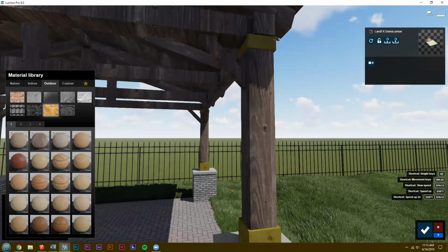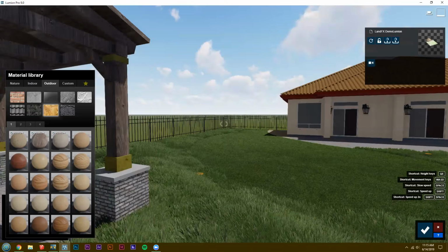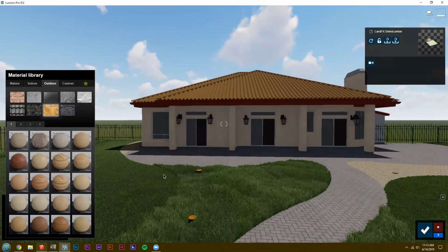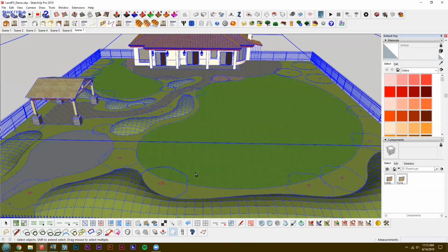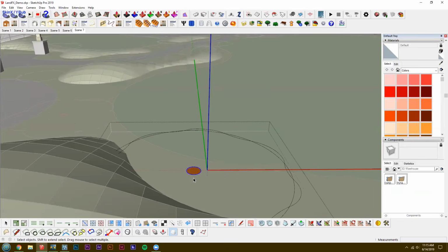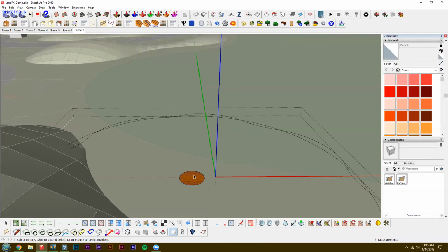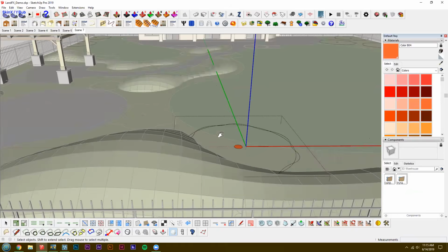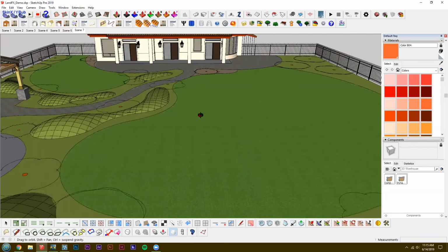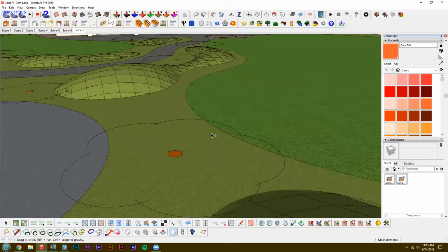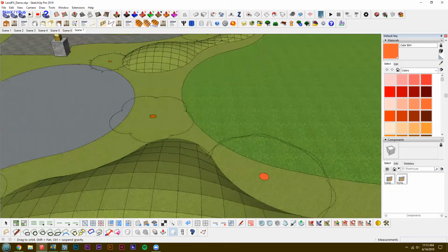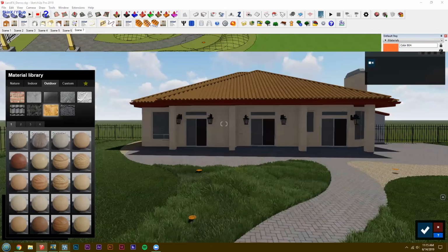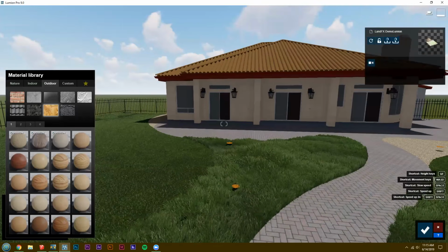Okay, so there is a difference. In the SketchUp file, these are actually just from land effects. Since they're all components, I'll go in and close this face and texture it something bright so I can see it. And then hover them about 6 inches above the ground, just so the grass and stuff doesn't cover it. So it's basically just floating geometry.